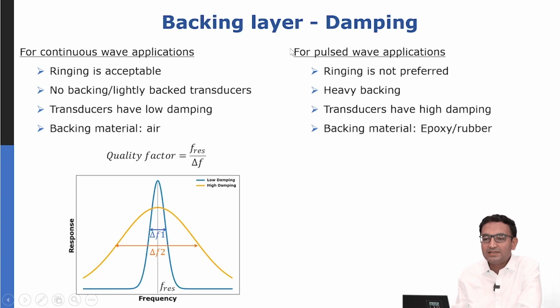So, like I said, for continuous wave applications, we don't care that much about ringing. Ringing is acceptable. What we need is very good power transfer for continuous wave applications. So therefore, we go for either no backing, which means it's air backing, or some lightly backed transducers.